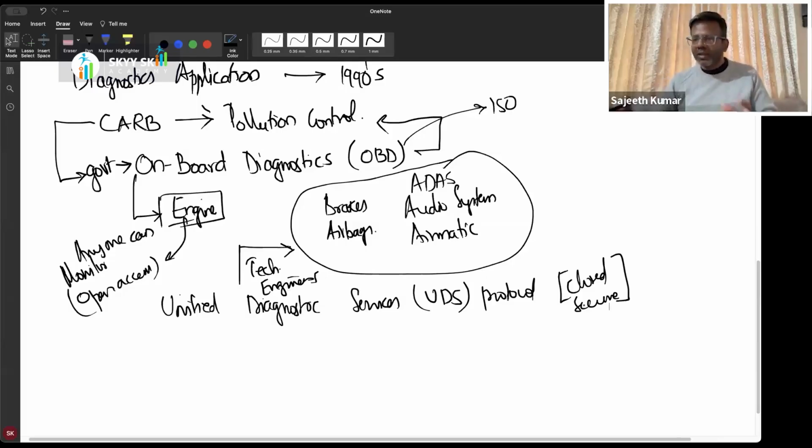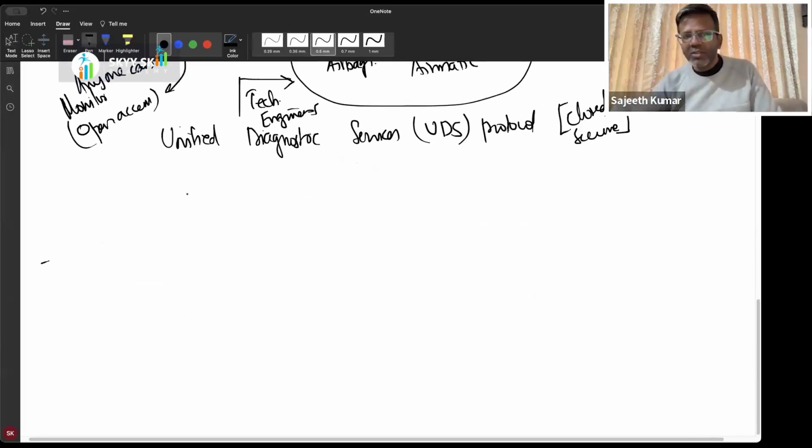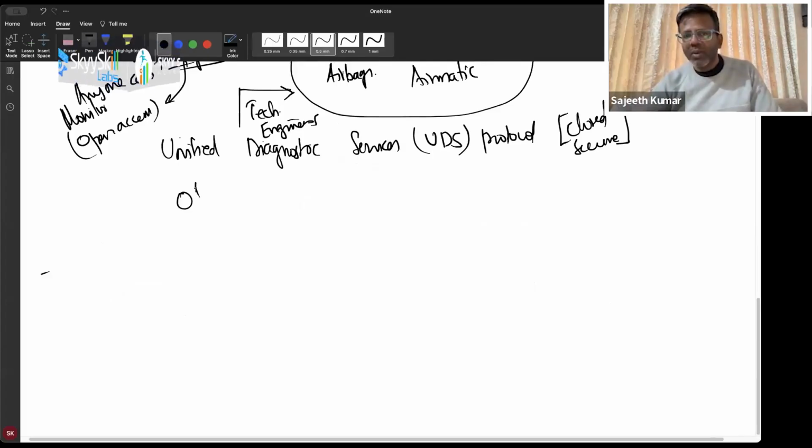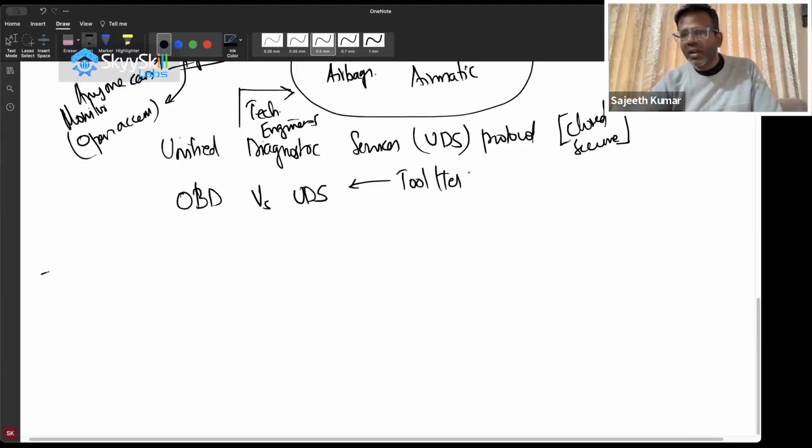Okay, so I just wanted you to understand the background about what diagnostics basically means, because very frequently, when you start talking to people, OEMs or something, they'll talk about OBD, which is onboard diagnostics. They'll talk about UDS, Unified Diagnostic Services. Now, a tool which helps you perform UDS services, we basically call it the tool or tester.